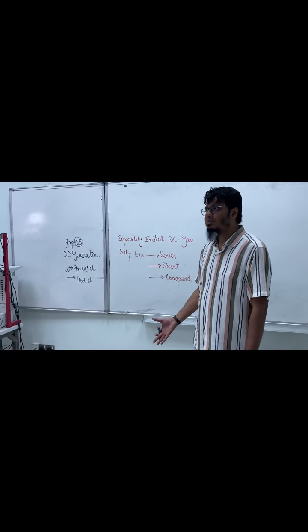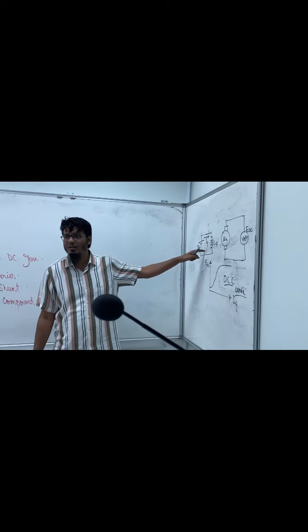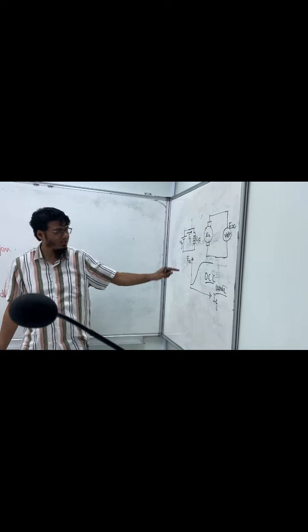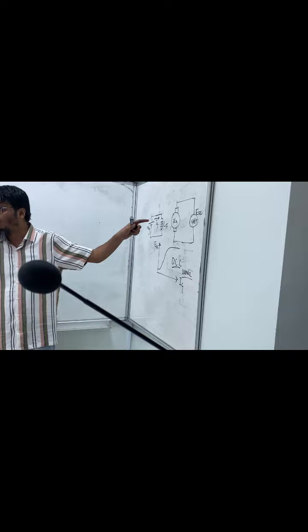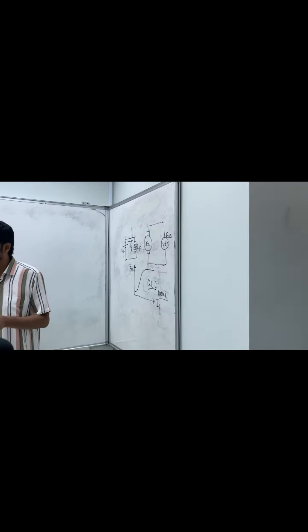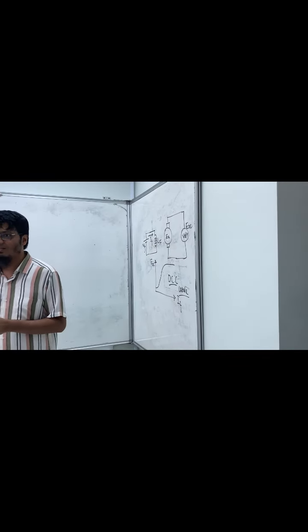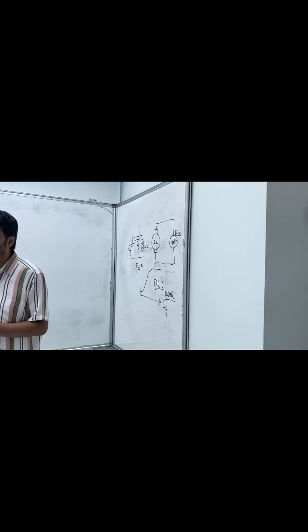We use separately excited. Why? Because only in the separately excited generator we can control field current. Are you with me? Yes. You see, in the x-axis we have IF, right? So to get a good plot, we need to have control on IF, right? So in the separately excited DC generator, we have a separate voltage source for field. So we increase slowly, and we press F9, and we get the curve.